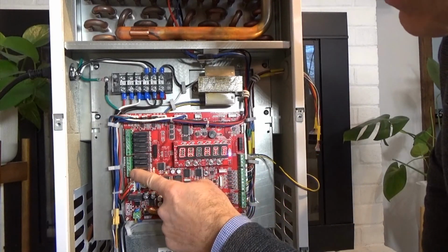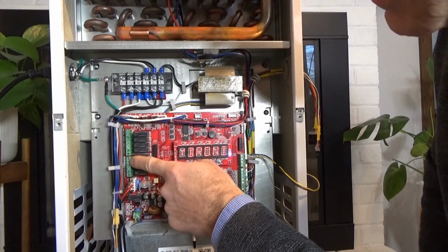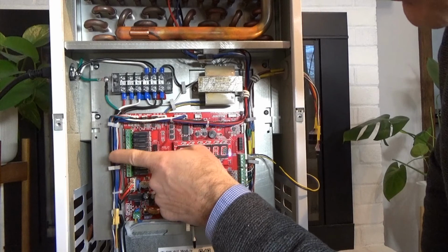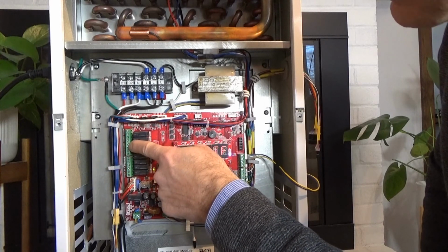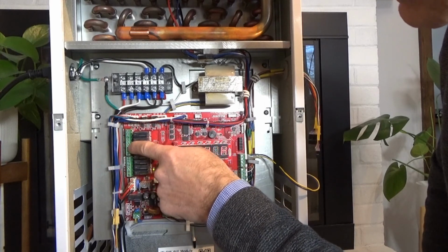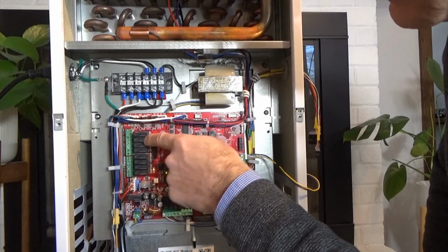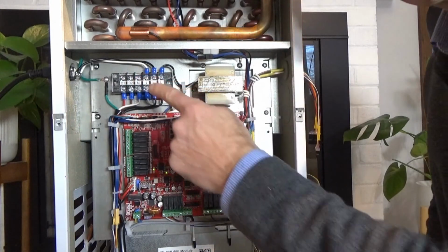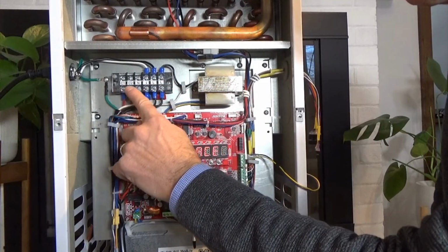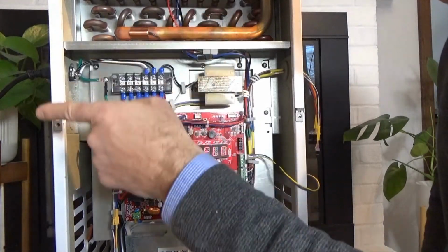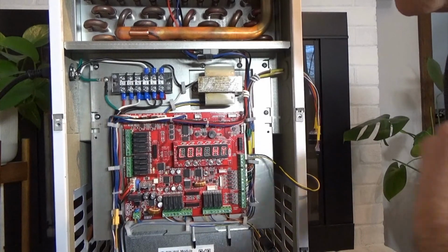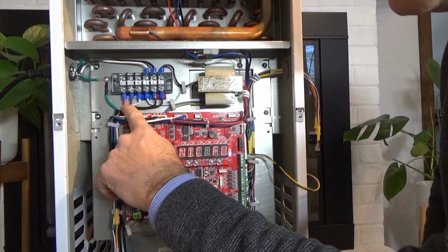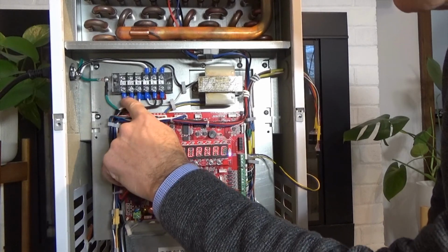So we talked about the output to the compressor, output to the heat pump, your TT to the boiler, your humidity sensor, your humidifier output, your dehumidifier, which we're not using, and then your 24 volt to your circulator. And then as we looked at, we've got the C1 and N to our pump that's supplying hot water to the iFLOW, and we're modulating or controlling the variable speed through this red contact.